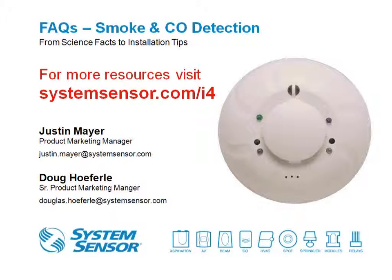Doug, is the smoke detector portion of the I-4 unit field serviceable, and can it be taken apart and cleaned? Yes, the cover of the smoke chamber twists off and can be removed, and the smoke chamber itself can then be pulled straight up and removed for cleaning.